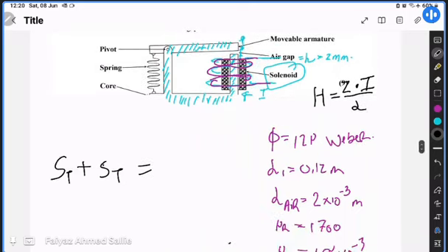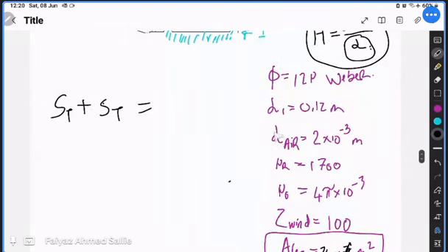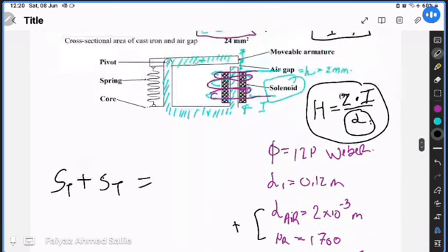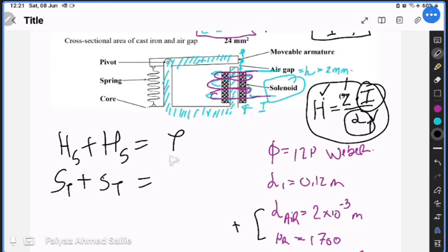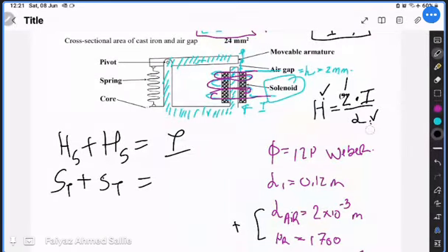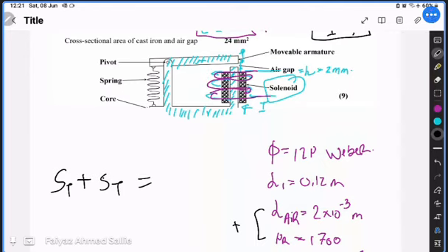Oh, sorry. This is the formula that students are using and failing in. So for this length, they use this formula and then they just add the length. They add these two lengths over here, and then they substitute it over here, and they calculate this one, and then they get current. That is absolutely wrong. We have to add the strengths separately and then get the current, which is the other method. But we're going to focus on this method here of calculating from the reluctance, right?